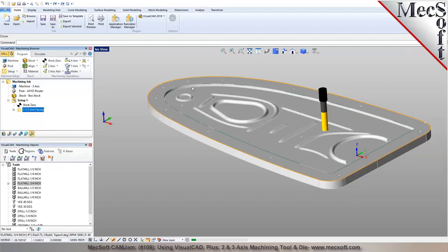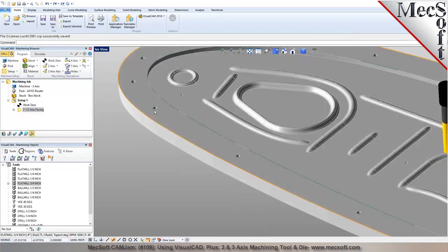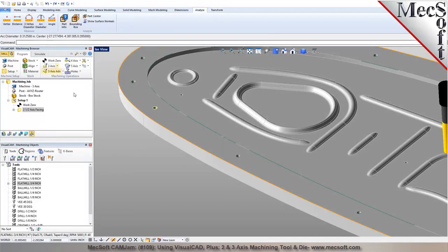So then in the next step, you want to go ahead and take care of machining these holes in here. I know we measured the diameter of the holes. These were, if I go back and verify it here, analyze that arc diameter, they were 0.3125. So would you have a drill bit of that size, or would you do like a pocket machining, or how would you like to go about machining those?